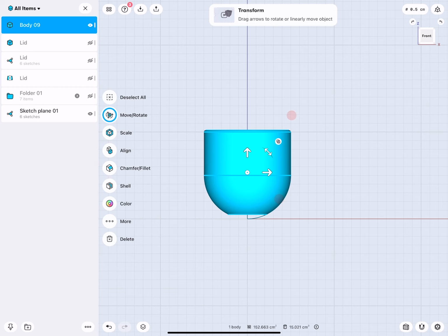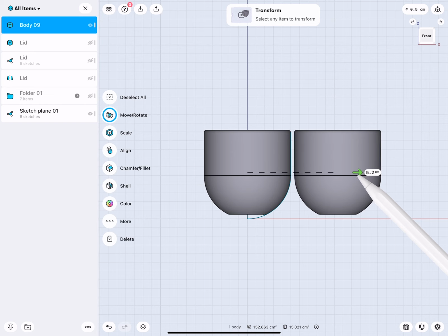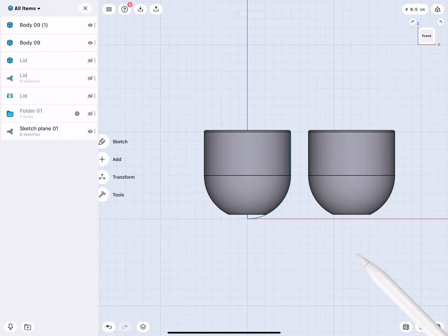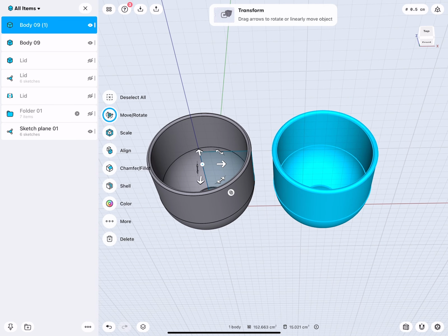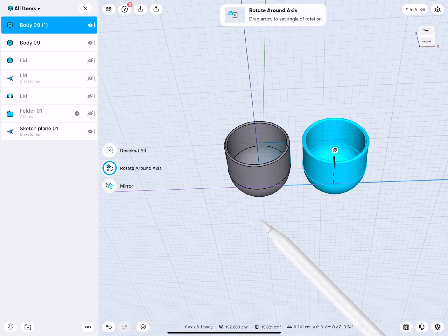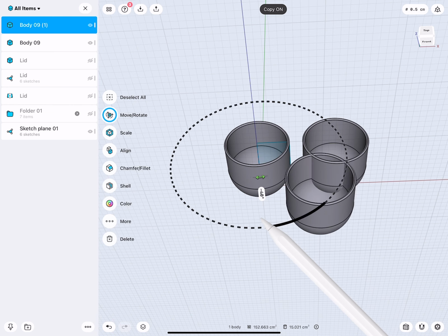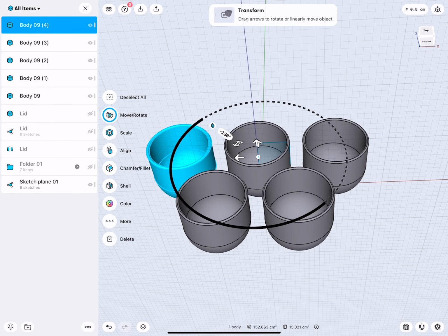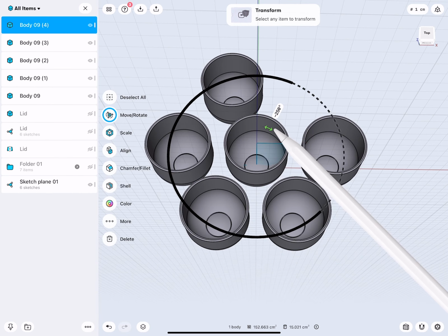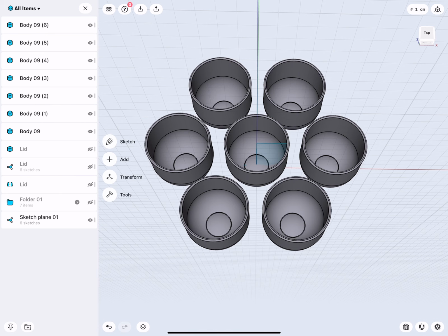It's also very easy. We make here again a copy. So to 6 centimeters. Because I have grid snapping turned on, everything is easy to do and precise. I snap to the center line and then I do the same. 60 degrees, 120, 180, 240, and 300. Very good.